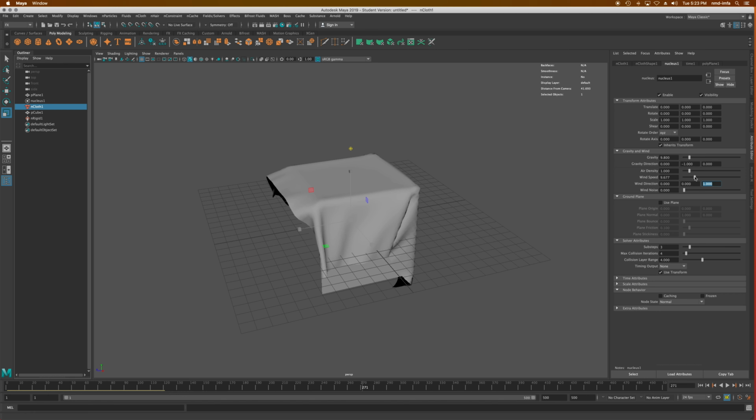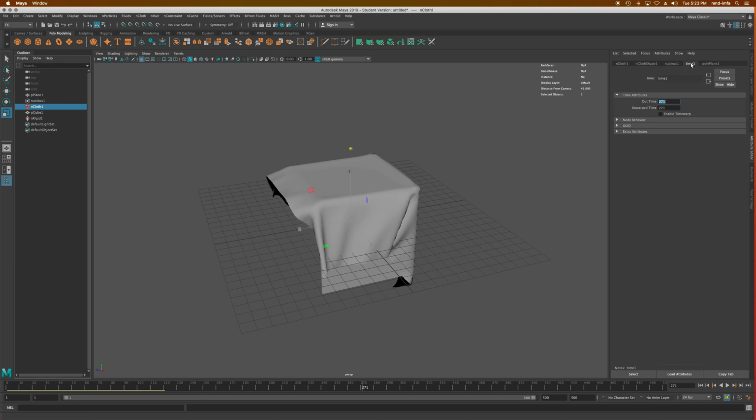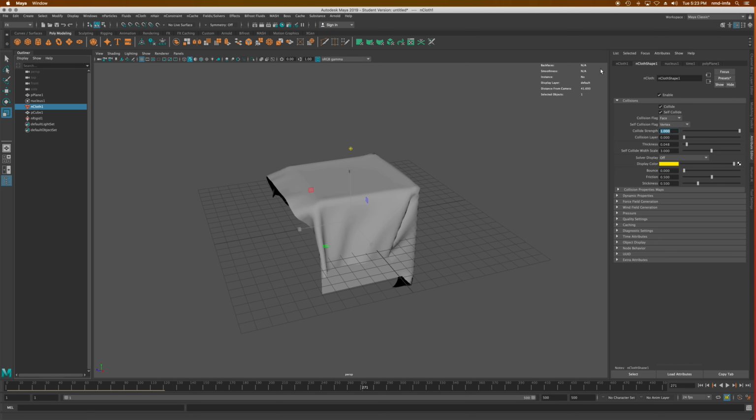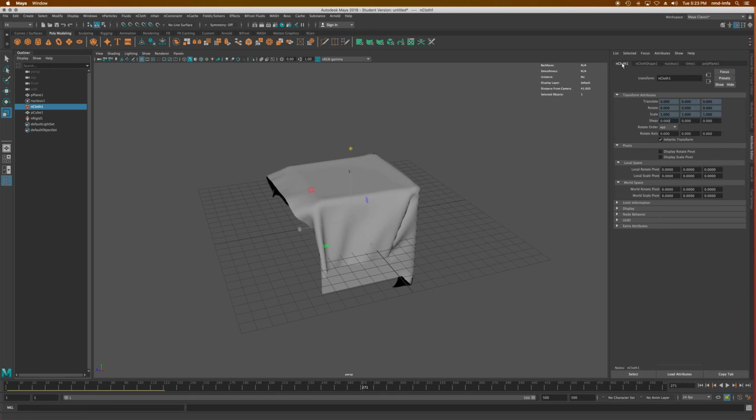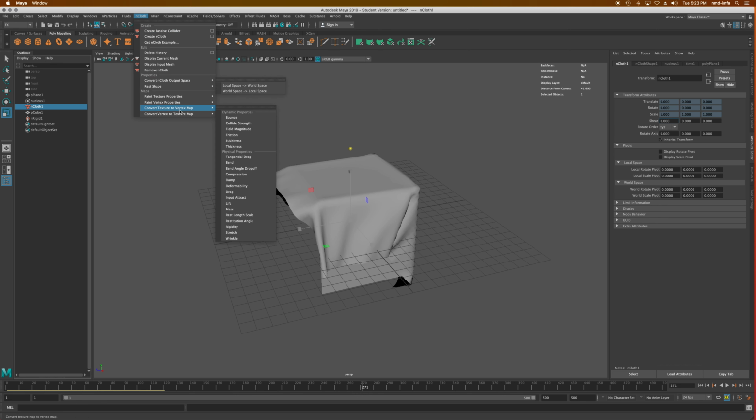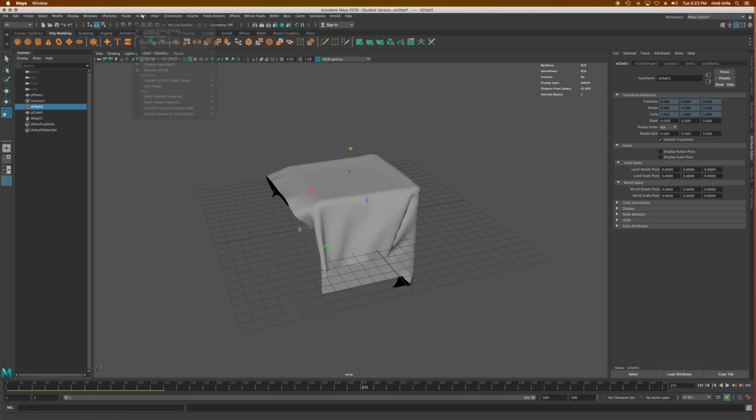You can bring in a ground plane so that there's a ground plane that it would sit on and doesn't fall all the way through. And yeah, I think that's a good place to stop to get you started. There's a lot more in here, obviously, but that's a good place to start. Start with some NCloth, make a simple collider, and then we'll go from there. You will continue to use this create passive collider with other types of N particles as well, but all the other NCloth is in here as well. In future lessons we'll look at adding some constraints, some elements that hold them in place.